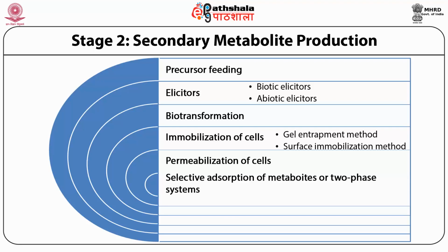Some of the materials used for the removal and sequestering of the product are polycarboxylic ester resins and neutral polymeric resins, which can adsorb these secondary metabolites. In a few cases, activated charcoal, RP8, which is a lipophilic carrier, zeolites, polyethylene glycol, and cyclodextrins are all used to help in separation of the secondary metabolites produced, so that the process is more efficient.